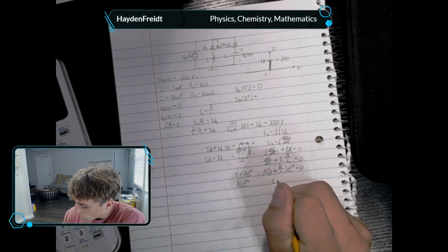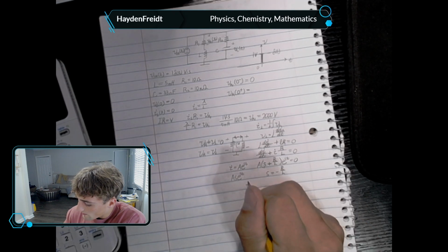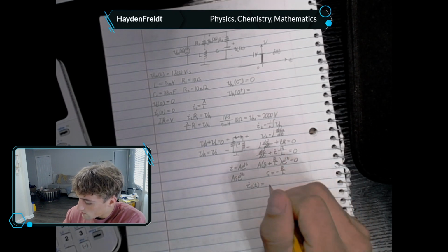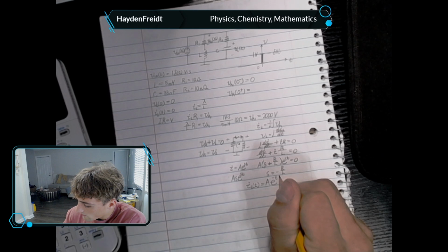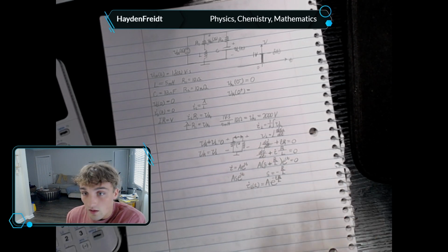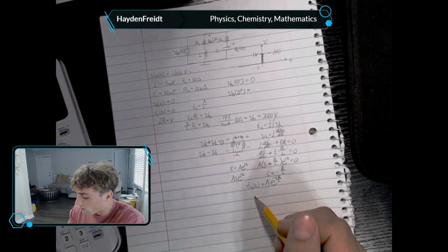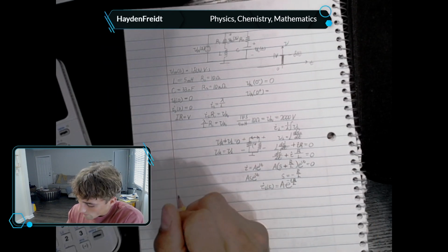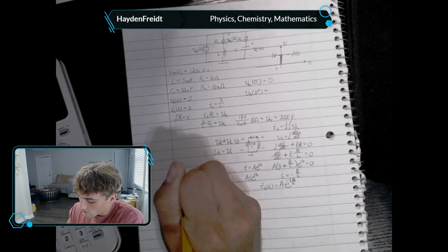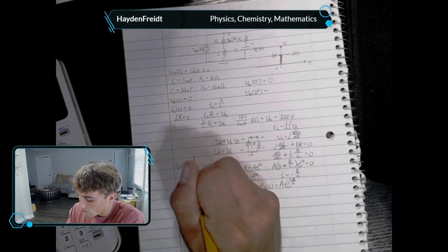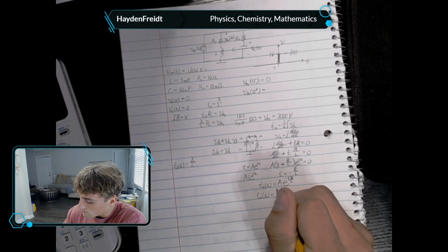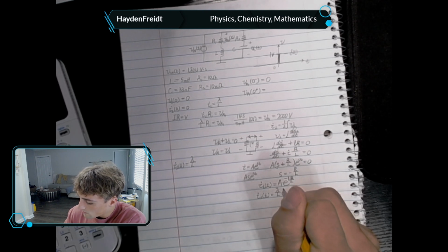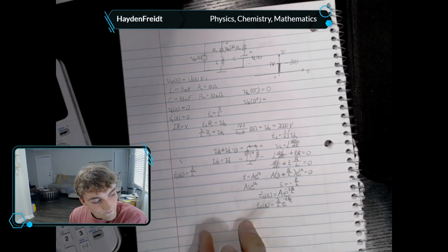Okay, anyways, continuing forward, s equals negative R over L. IL of t equals A times e to the power of negative t R over L. Okay, so it's going to look something like that. We're going to define A by our initial conditions. So IL of 0, that's at the time of the impulse, equals lambda over L. That is true. IL of t equals lambda over L times e to the negative t R over L. We don't have a particular solution because we don't have a drive.